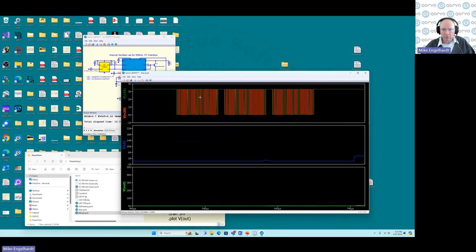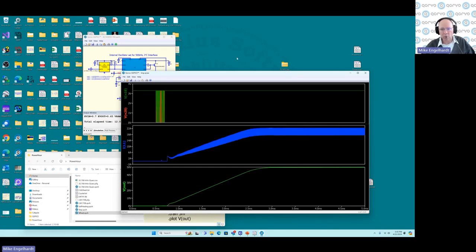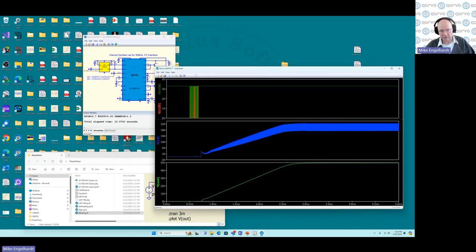So it first writes 3 bytes. The first byte programs the soft start, the second one programs the gate voltage, the third one enables it. But you can program the dead time. There's about 100 parameters. There's 63 I squared C registers, and there are 2 bit fields that control about 100 aspects of the part, and everything is modeled in this because in QSPICE it's easy to present an infinite amount of digital logic to your SPICE simulation.